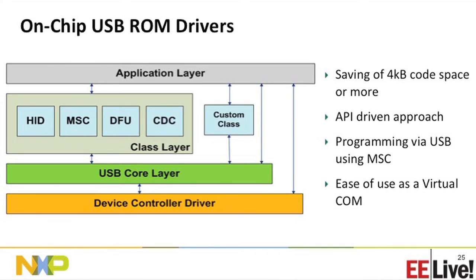Here we talk about some details on the ROM driver. On the ROM driver, we support HID, MSC, DFU, and the CDC class. DFU stands for device firmware upgrade. Basically, the device will enumerate as a mass storage drive on the PC, and you can see there's a binary there. You can change that to whatever binary you want, and you have already updated the device. It's a very convenient and simple operation. Certainly you can also build custom classes based on our low-level drivers.